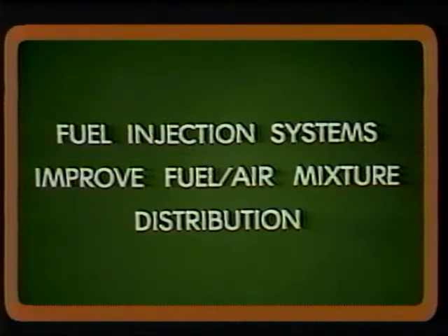As you can see, the pressure carburetor overcomes many of the limitations of the more simple float carburetor. It is not affected by the attitude of the aircraft, and it is not susceptible to the formation of carburetor ice. Pressure carburetors still have their problems, though, because their fuel is injected into the airstream at the beginning of the induction system.